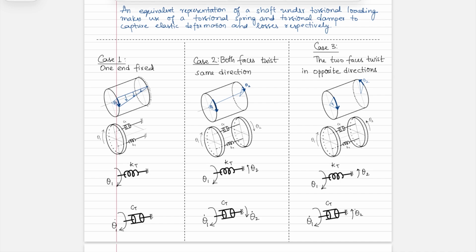So the spring is going to create a resistive torque given by tau s is equal to Kt times θ1. And what the spring is experiencing is going to be a torque of this tau s, as defined now. Remember that this theta is a measurement, while this here is the torque. Why are they equal and opposite in direction? That's because this torsional spring is massless, and so the net result of this will be equal to 0 only when tau s on both ends are equal and opposite.